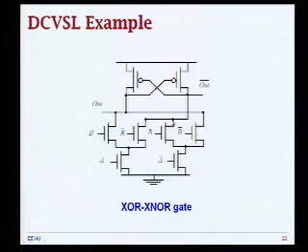And you are implementing the inverse of that, because that's the pull down. Right? So now this is XNOR and now this is XOR. What you can also see from this example is that you can share transistors for reduced area. Basically you share the bottom transistors A and A bar, and you can then just build on that and implement the complementary function.